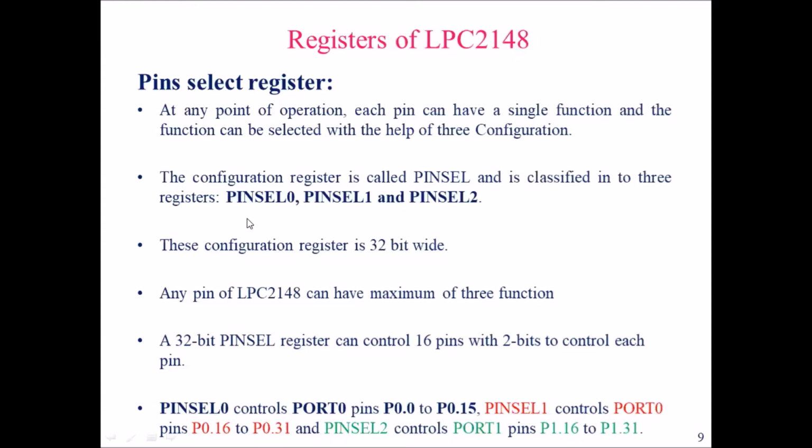As I told, the size of each pin select register is 32 bits wide. In this 32 bits, each register can control only 16 pins, with 2 bits associated to control each pin. This is the important point.